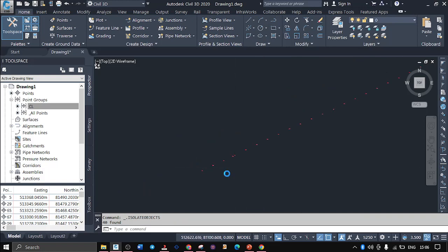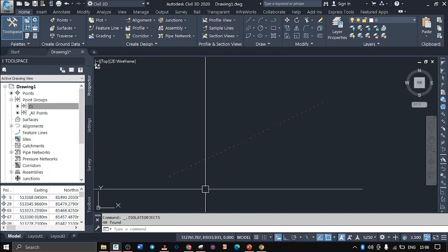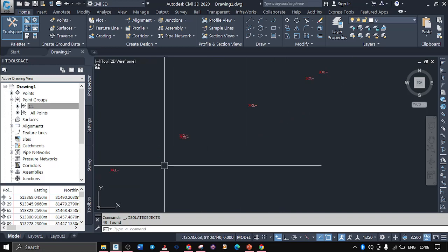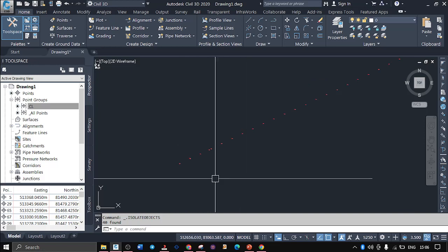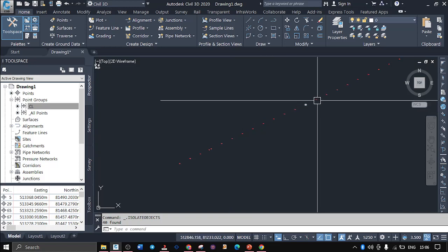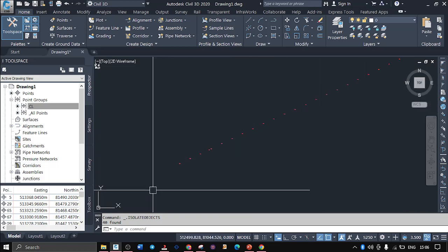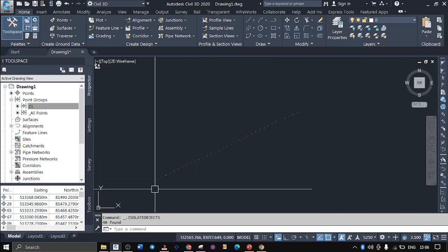Have you seen, Bwana engineer? I have only selected points with CL only. So now here I'm able to connect these points very well to do my center line of the road. You get it? Yes, I get.